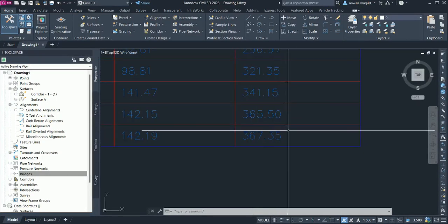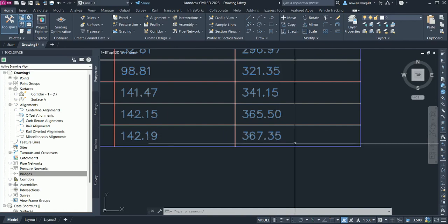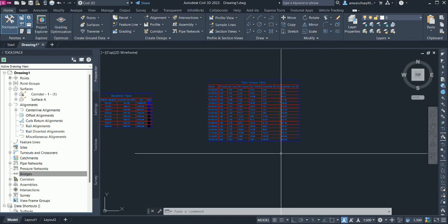So these are the cumulative data. If you are making cross sections in CAD or in some rough estimate, it will not give the exact data like this. It will also give the expansion factor. You want to apply some rock type and need some more expansion. Like if you are going to hard rock excavation, the expansion factor for hard rock is very high.